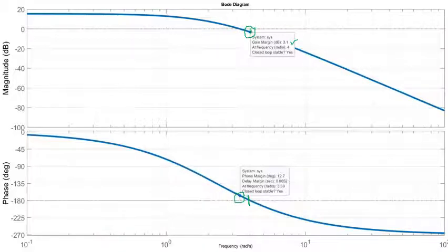So this is at the frequency 3.39 or 4, and this frequency is coming as 4. At 4 the gain margin comes out to be 3.1. This can be easily verified. Since my pointer has moved a little, you cannot see the exact value of the frequency, but it lies in the same range. You can easily see that the gain margin we have attained is 3.1.